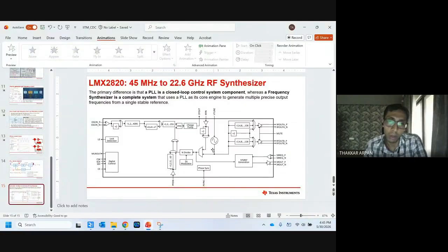So the on-chip quality factor of all these oscillators, best case, is going to be within 40 or 50, even at a frequency of around a few gigahertz. So overall, the quality factor of on-chip oscillators you can generate is going to be 40 to 50. Once you have that bad a quality factor, it will not have a very clean source. I mean, it cannot generate a very clean output clock. It will have a lot of noise, right?